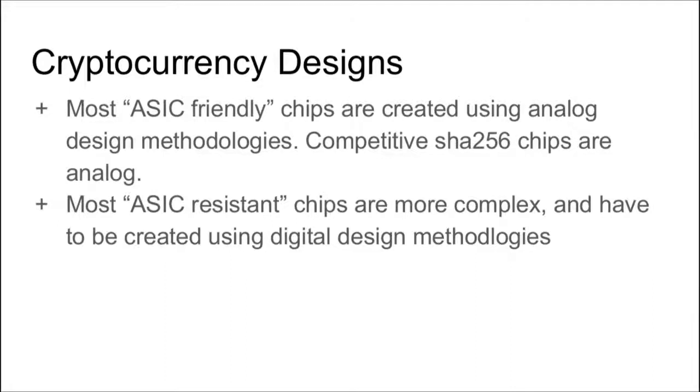So all Bitcoin chips that are competitive are analog, and that's because the SHA-256D circuit is relatively simple, and it's also a static target. So for example, in the GPU world, NVIDIA is not trying to make a theoretical GPU. A GPU is trying to hit a target set of use cases, and as the world grows, that set of use cases is a moving target. If you're spending too long optimizing a chip, it doesn't work. In Bitcoin, SHA-256D is not a moving target, it's static.